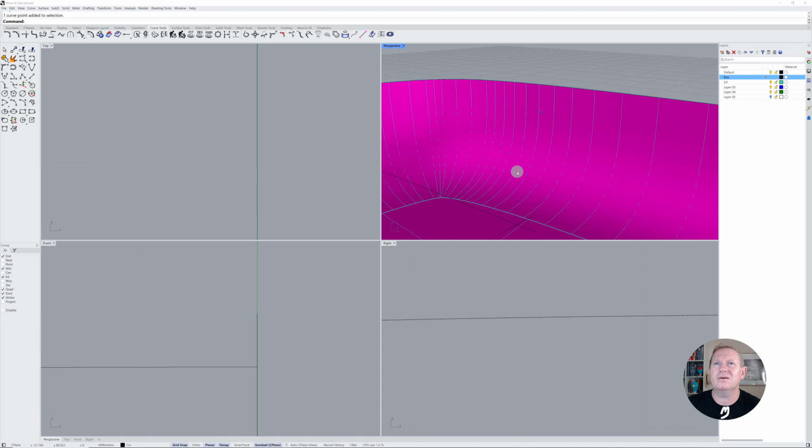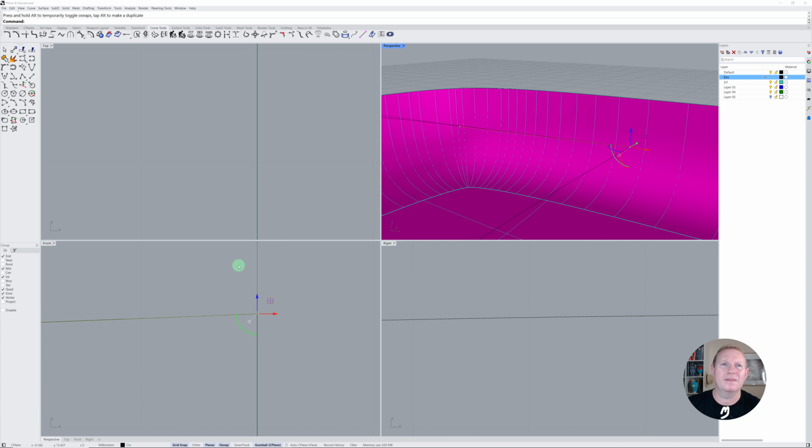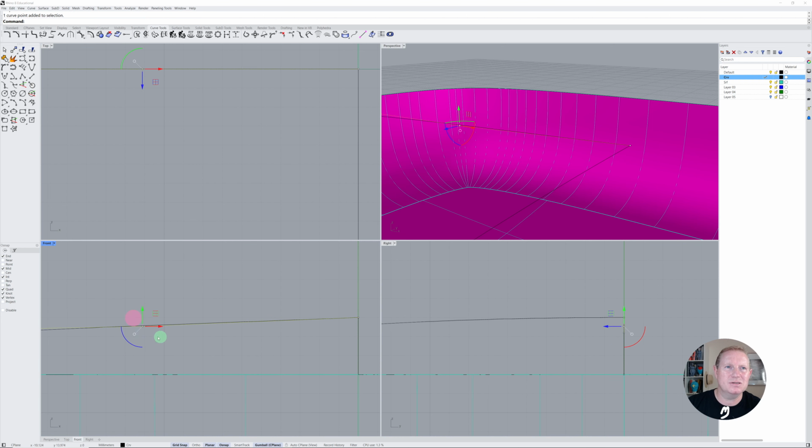So I want, in the 3D view, this control point, and I want to move it up to the end there, like that. Okay, and then because it's back onto the grid, I can choose that point and I can pull it up onto the grid. Whoops, grab that point and lock it down onto the grid. There we go. Now it's perfectly straight.